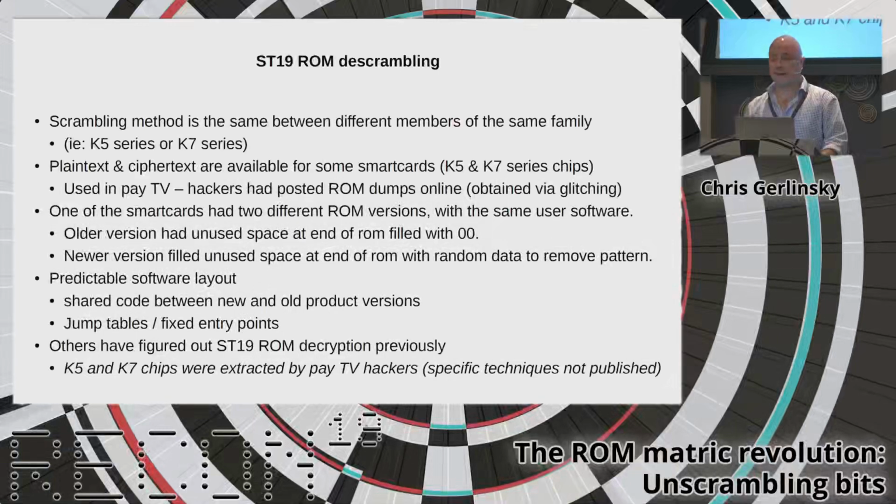In my case, I actually extracted the bits from the newer version first, and I went to do a second one just to identify if I had any errors. And when I went to do the second one, I saw that it was actually a different ROM with all this empty space with the patterns showing through, and it would have been so much easier if I'd started with that one. So sometimes it's worthwhile to look around at the different products, because some of them might have more obvious patterns that you can look at.